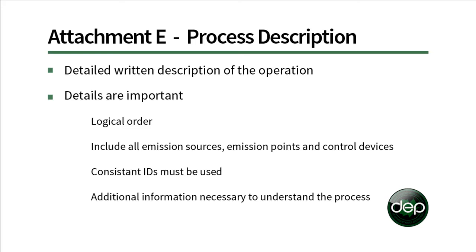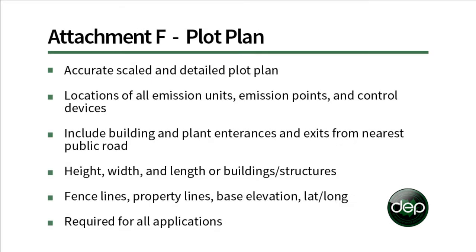We'll need a plot plan. Please submit a scaled and detailed plot plan of your facility, where all the emission units are located, where air pollution control devices are located, how you get to it off of a main road, where the building entrances and exits are, height of stacks or buildings, things of that nature. Please list, try to be where the fence lines are going to be.